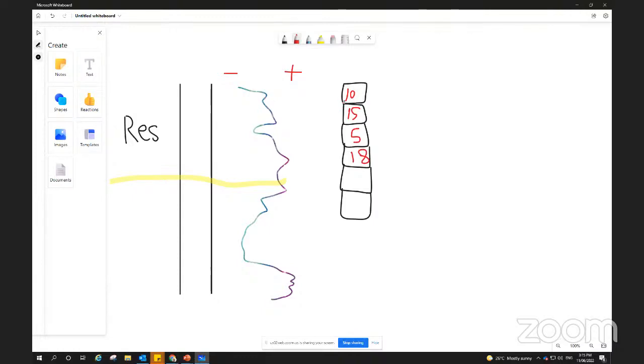So you have cells which have values that follow the same trend of the input data. You have here an average porosity of 10% in the input data, and the cell has a 10% average. Here you have a 15% average, then you have 15% inside the cells. Otherwise, it's not capturing. If it's not capturing, you need to scale up again and put smaller divisions for the cells. So the output curve, if you are taking the output, should be like this.